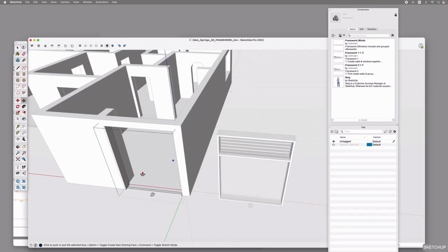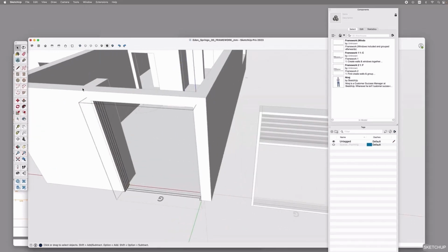Then I select my left window frame from left to right, as this will only select everything that is included in my selection. If I select from right to left, it also selects the bottom lines, which I don't want. Then I group this part and copy this object to the right side, as it is identical. I could use my flip tool to flip it, or if you work on older SketchUp versions, you can right click and flip it in the correct axis.